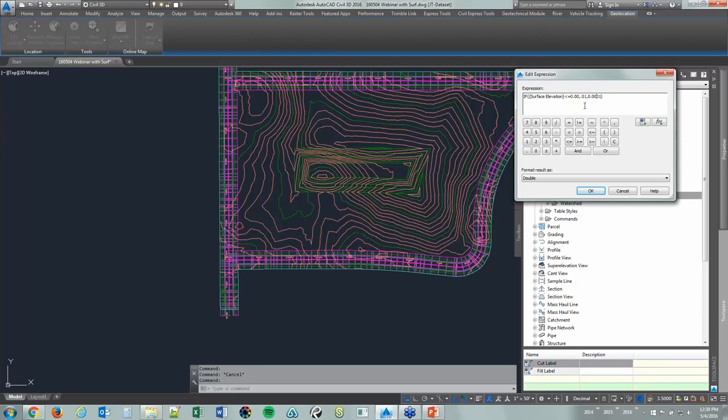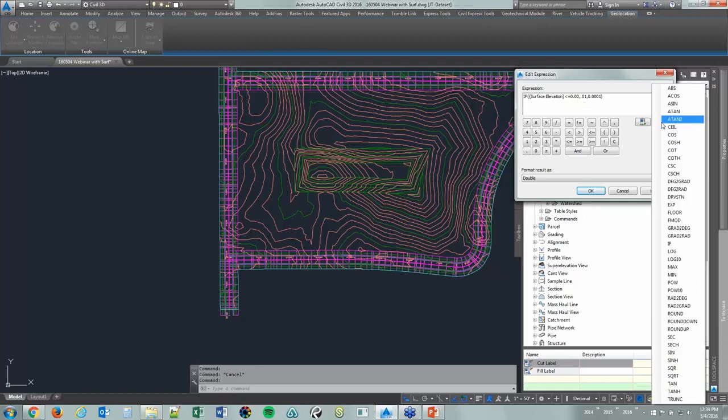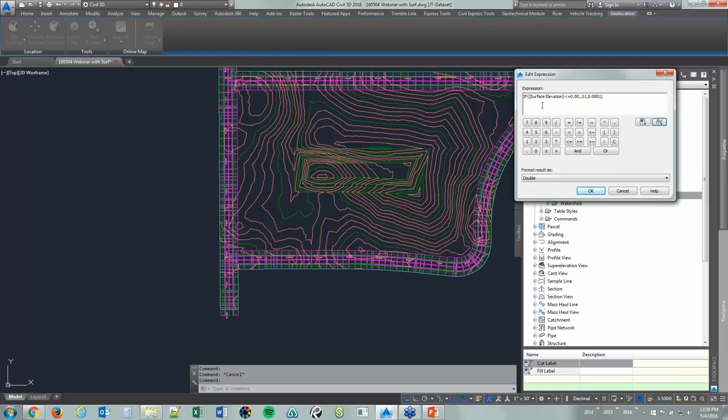One more 0 in there just because I know that comes in real big. But what it's saying is, we have this if statement from the option on the right hand side, and then we have surface elevation selected, so we drop those two pieces in. Pay attention to the parentheses here: it's if, that'll drop in the front parenthesis for you, and the surface elevation comes in brackets. I select here, and actually for cut, I don't want the equals,